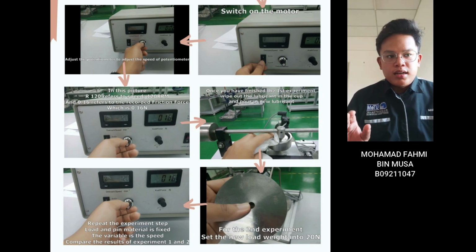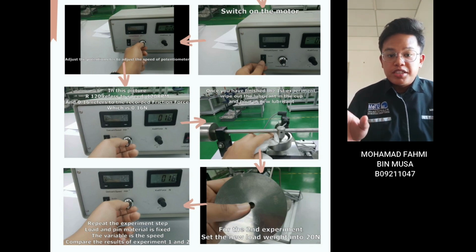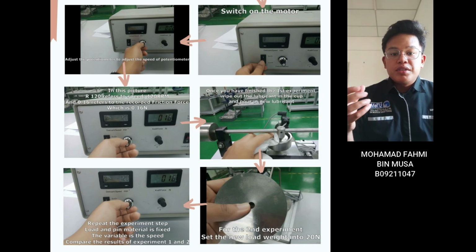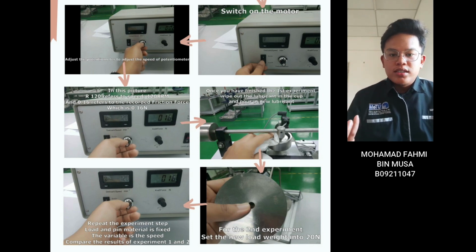We start with a 10 Newton load, and then 20 Newton, 25 Newton, 30 Newton and 40 Newton. If you want to add on the load, we don't need to switch off the machine and start from the first procedure. We just add on while the machine is running. The observer needs to record the data after we add on the load weight at the end of the loading arm.